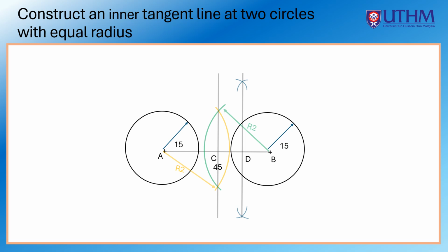That is a point D. Next, divide line AC into 2 sections at point E. Now that is a point E. Then create 2 circles at point E and D using the radius of AE and DB. These 2 circles cut the previous circle at point S and T.